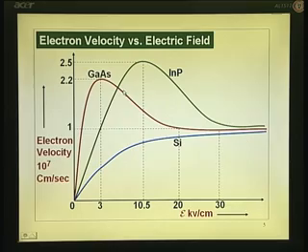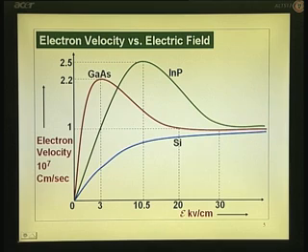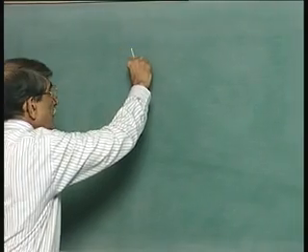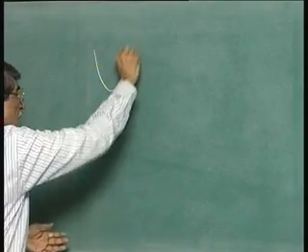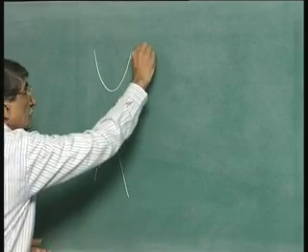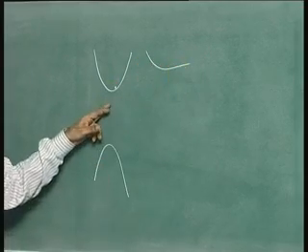It is more than the energy required to transfer the electrons from the lower valley to the upper valley, but it takes finite time for the electrons to transfer from the lower valley to the upper valley. So, during that finite time, before it is scattered to the upper valley, it is all the time in the lower valley. As a result, electrons are all the time here.